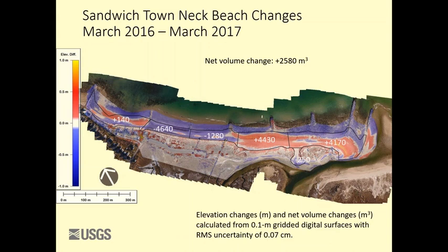And we can look at a bigger picture of the whole beach. Unfortunately, the other problem with this, of course, is it's all subaerial. We always map at low tide, but sometimes the tide's lower than that. We've got about a 12-foot tide range here, so about a 4-meter tidal range. Sometimes we get out pretty far, and other times we don't. This outer line is roughly the mean low water line. And this particular map lets us look out a lot farther, but these numbers don't always capture that.